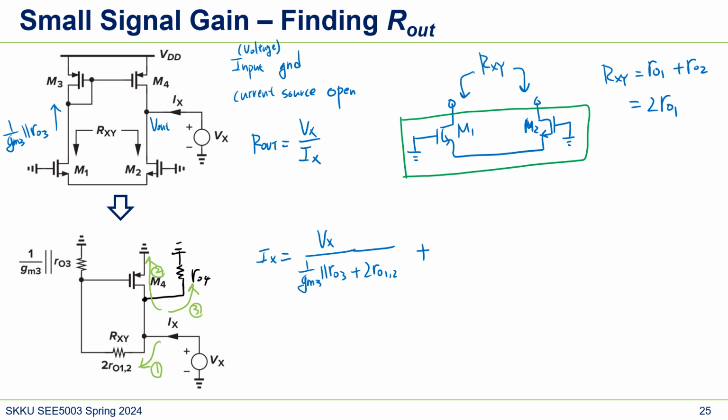And what about 2? The current flows here, right? And that changes the voltage here. And that will also control this PMOS, and that will make the current flow. So let's see, if current flows here, the voltage here increases, right? Because V equals Ri. So if current flows here, the voltage increases. And here's VGS4. Let's say this is VGS4.